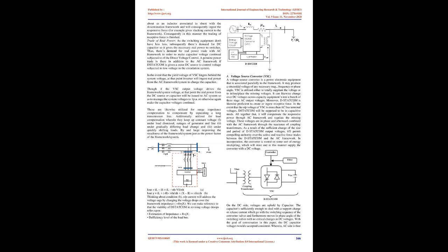Exchange of reactive power: if the output voltage of the VSC is greater than the system voltage, then the D-STATCOM acts as a capacitor and generates reactive power, i.e. supplies leading current to the system. Whereas, if the output voltage of the VSC is less than the system voltage, then the D-STATCOM acts as an inductor connected in shunt with the distribution system and will absorb the reactive power, i.e. supplies lagging current to the system. Hence the exchange of reactive power is done.